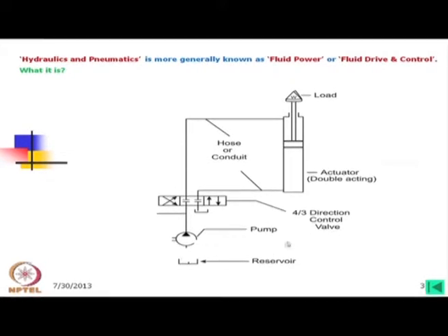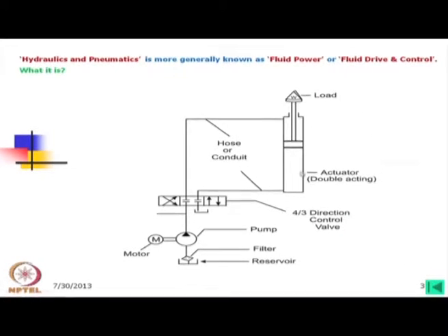Now, we need a supply of oil to the pump, which is called reservoir, sometimes it is called tank also, and of course, as we are pumping the fluid, we need a filter there. Now, this pump will be driven by a motor or a prime mover, which may be electrical, which may be an IC engine, which may be other means of drive. So, this is the basic things and this would work, but there is another important question, that if this load gets stuck,